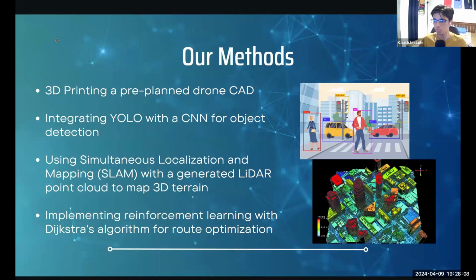Yeah. Okay. And then we also use a SLAM algorithm, which is simultaneous localization and mapping, which gives the drone or any autonomous vehicle a more organized way of searching. If we take, for example, a Roomba, the way it does it is kind of random, it just goes around the room for a while until everything is clean. But using a SLAM algorithm, while the drone or autonomous vehicle is moving, it generates an environment around itself and gives itself a location based on that environment, so that instead of going randomly for a set amount of time until the flight is stopped, it'll fly for the exact amount of time and space that is needed.